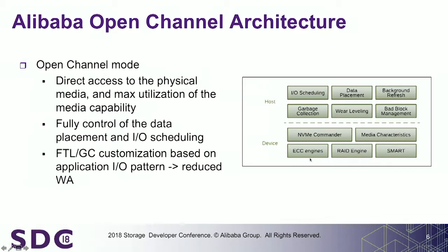There's no way for the host to do the ECC, and also the RAID engine, XOR, and SMART. For the FTL functionalities that impact data placement and I/O scheduling, we move all of them to the host side, including I/O scheduling, data placement, background data refresh, garbage collection, wear leveling, as well as bad block management.